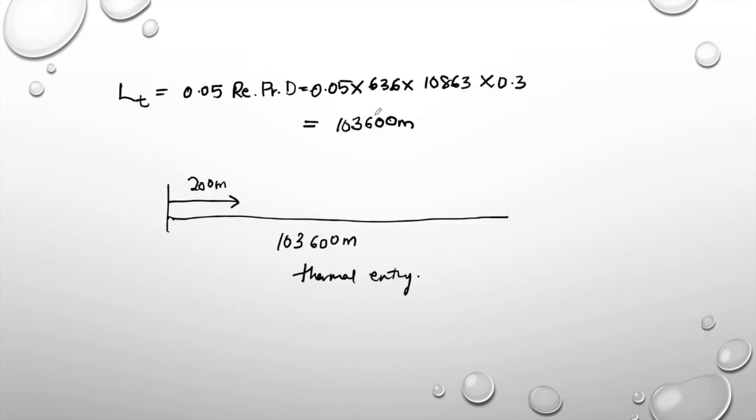From there, you can find that your Nusselt number is equal to 33.7. Okay, that is your Nusselt number. You have to substitute into the developing laminar region in the entrance region.